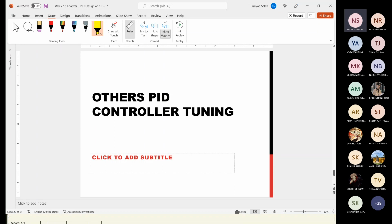Sometimes in a process, a specific tuning method is used. Let's say for maintaining temperature control in a chemical process, maybe you can use the direct synthesis method. But if you want to control the flow or the level, maybe you need another method. There is no widely accepted method that can be applied for a wide range of conditions. That's why you can see various formulas of PID controller methods.